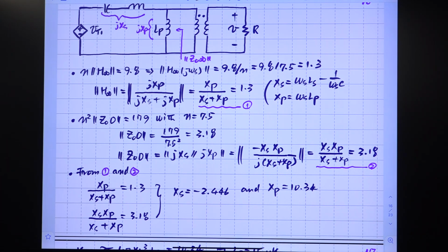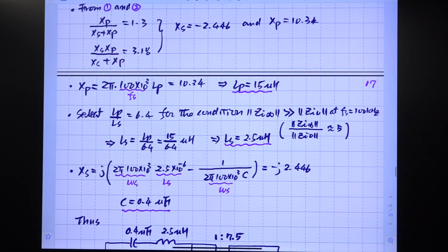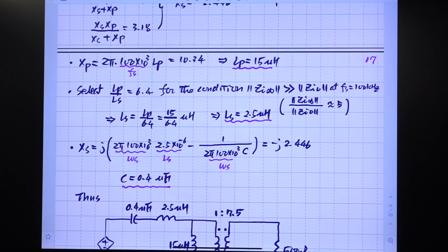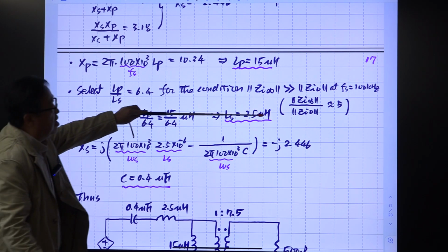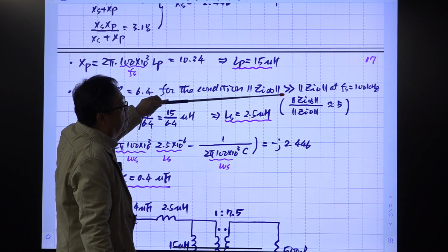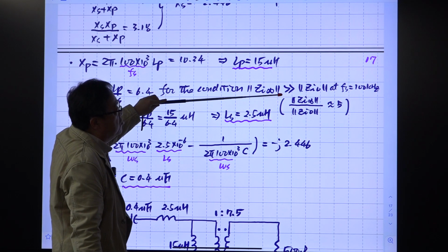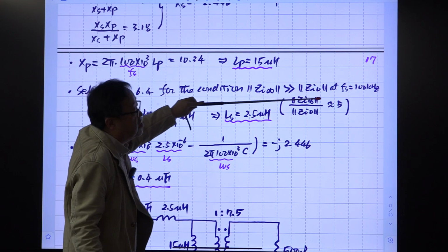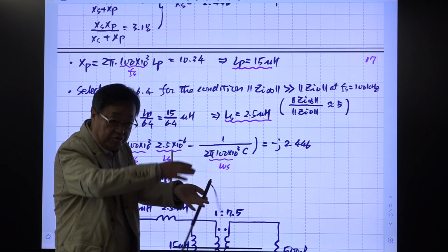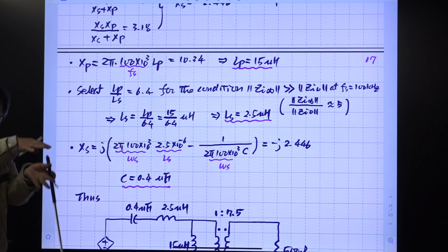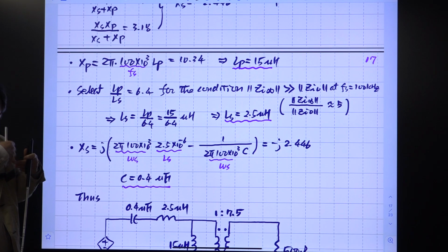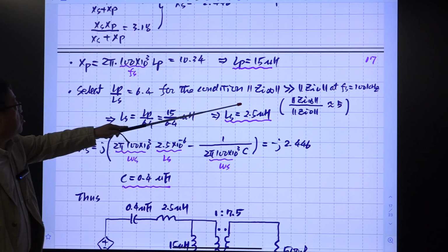Okay, you should have some justification for selecting that, because we initially selected this. Okay, at switching frequency, the magnitude of GI infinity should be 5 times larger than this one. Okay, because to have sufficient gap for the efficiency improvement. Okay, so we determined that.